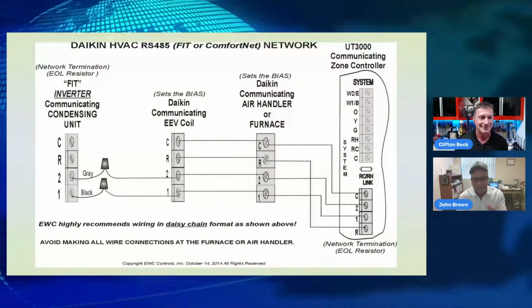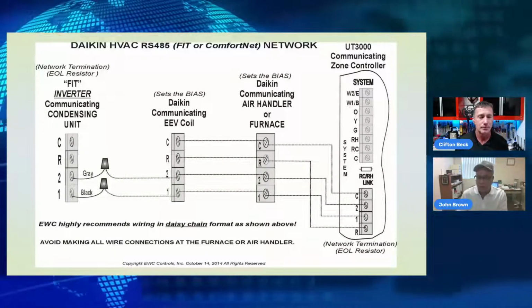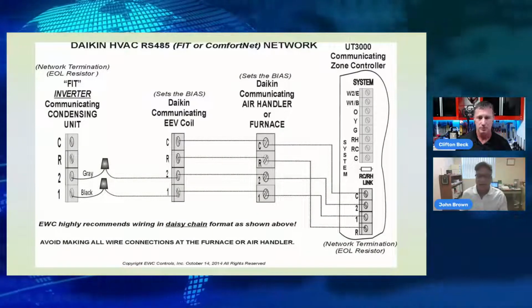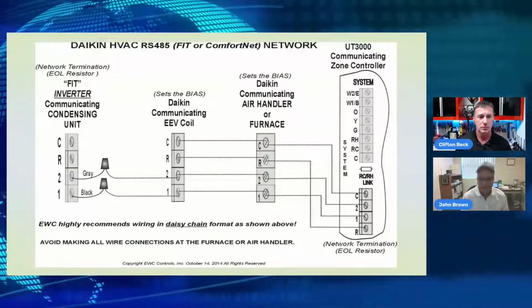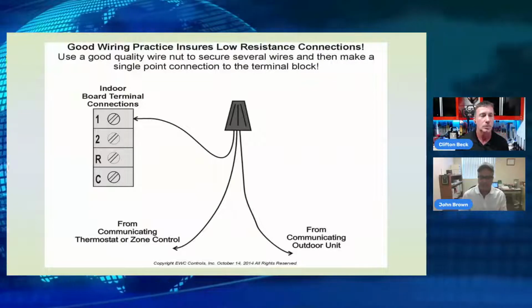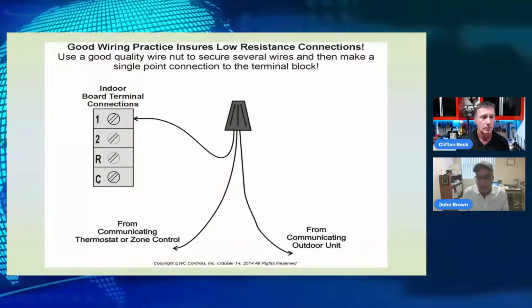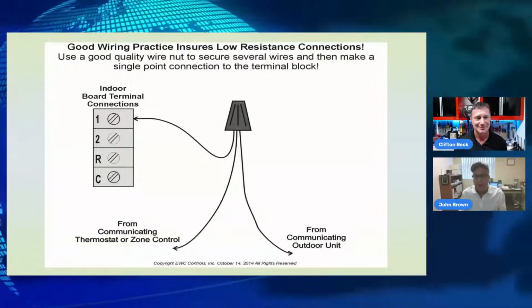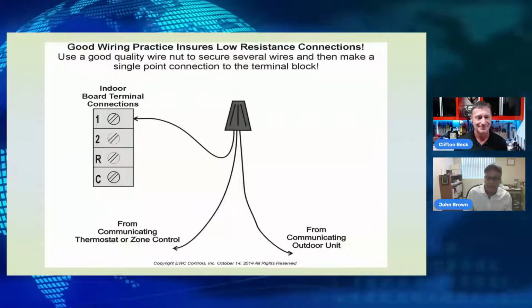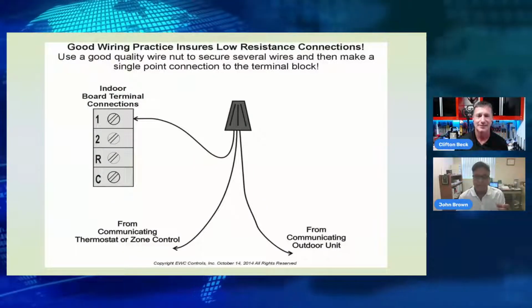Exactly. The fit inverter, when you place it into charge mode, which we're going to show you later on how to use the UT3000 rather than the thermostat to place the equipment into system test and charge mode, it will actually tell you whether the subcooling is proper or not and whether you need to remove refrigerant or add refrigerant from the system itself. So it's amazing, really quite interesting.